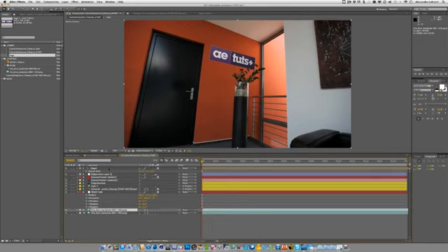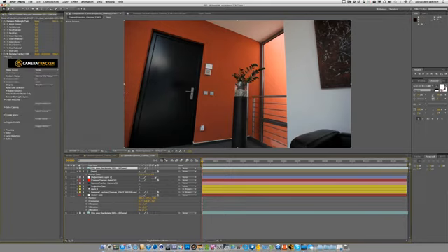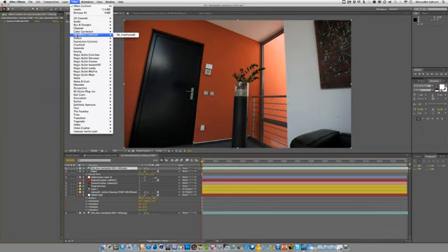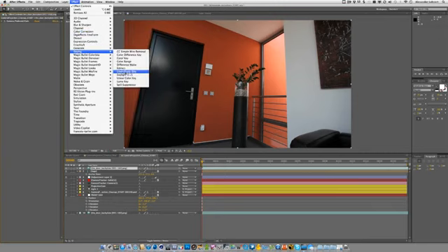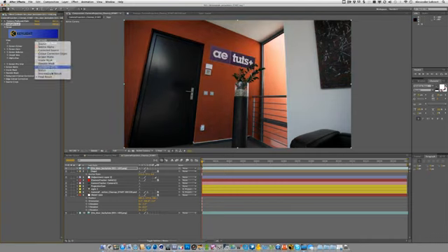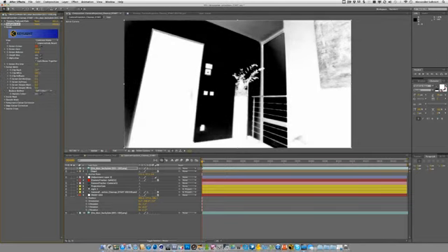Okay, so last step we are going to do is duplicating our backplate and just drag that on top, as we want that to be cleaned up for now. So I'm just dragging the camera tracker off a bit, and now we just go and say keying, key light, and let's just get rid of this red. Okay, in the combined mask, we just need to get maybe a screen blur of 1 pixel to get that a little bit smoother.